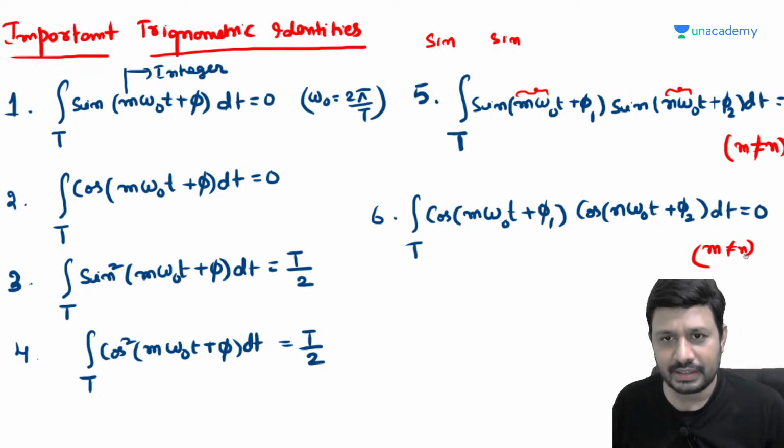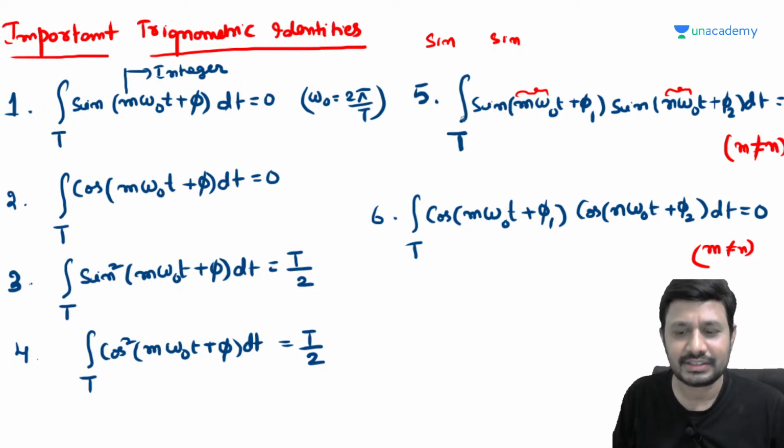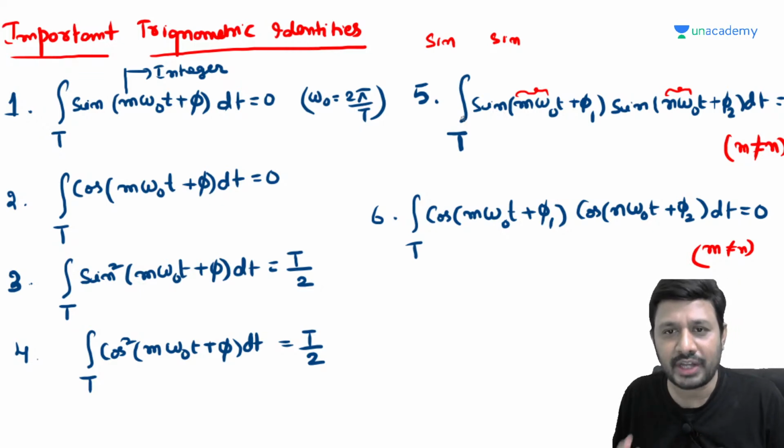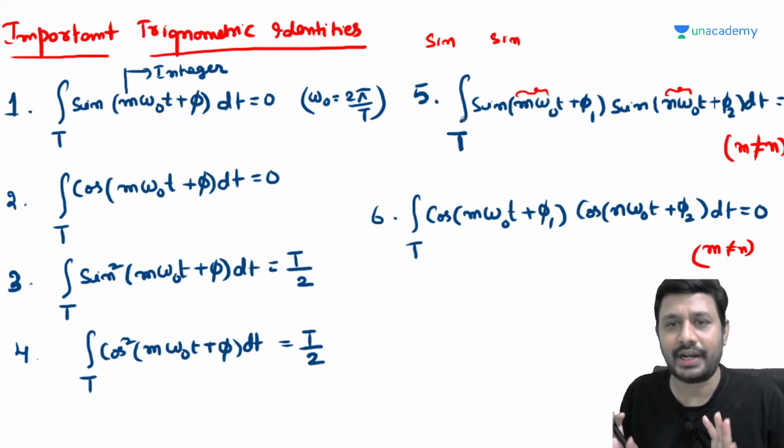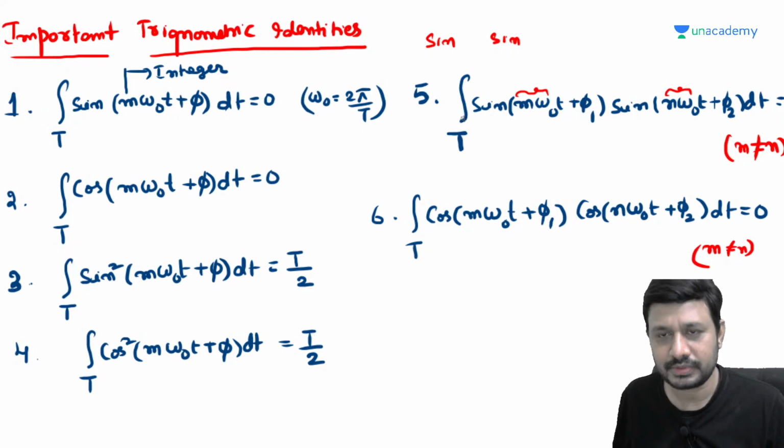Remember, in the first unit we studied that if two power signals are orthogonal, you can add the powers. If two energy signals are orthogonal, you can add the energies. Suppose your given signal is a linear combination of two sinusoids and they ask what is the average total power. You observe whether they are orthogonal or not, and only then can you add the energies or powers.